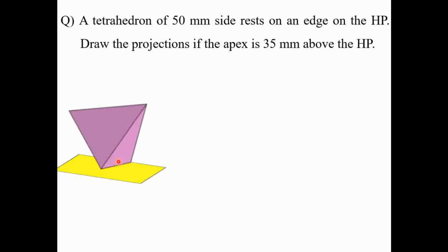But with the help of this shortcut method, we can identify that if one plane related condition is given, then that numerical has to be solved in two stages, and always in the second stage, you can observe here, HP related conditions we have to use.